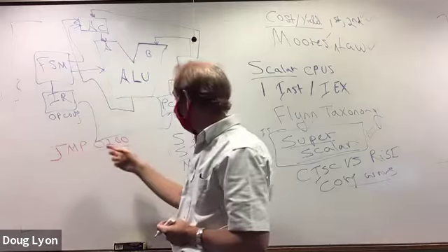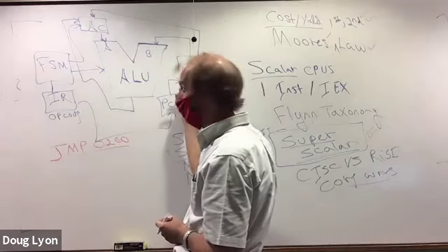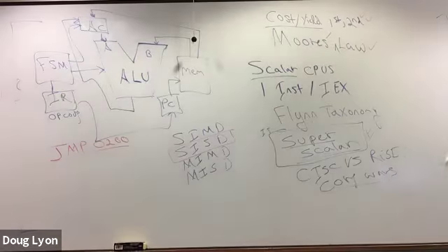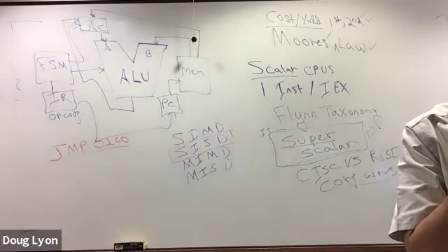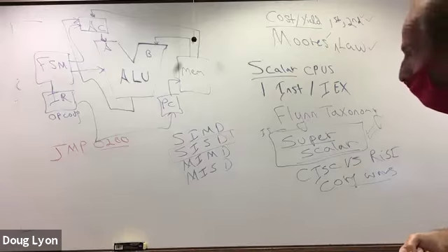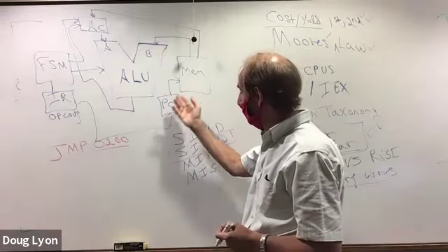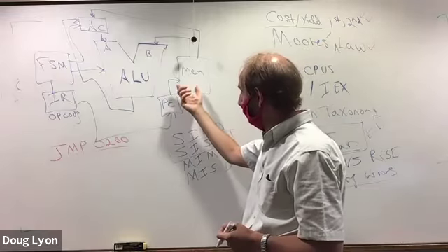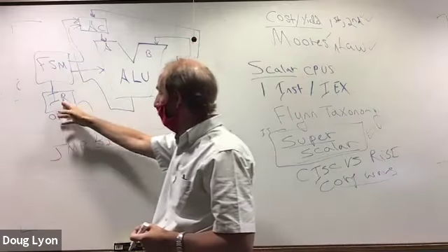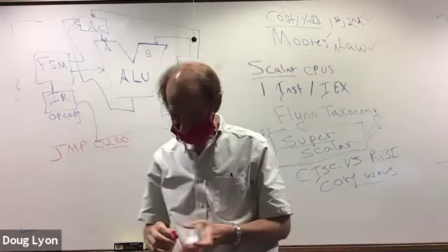He's saying to the program counter, I want you to go to address 0200 for your next instruction because we just did a branch, like going to the beginning of the for loop or to the subroutine down at this address. Once the program counter gets jam loaded with that, it'll fetch the next instruction from memory, and that'll end up in the instruction register and be decoded.